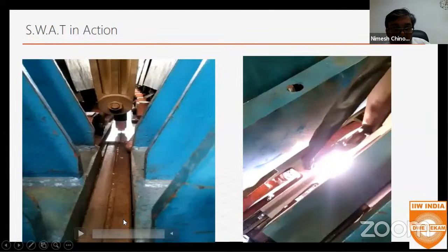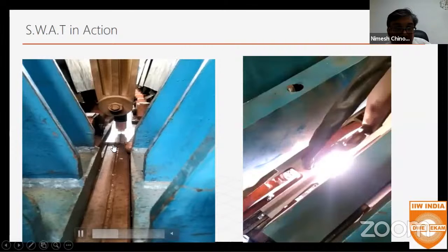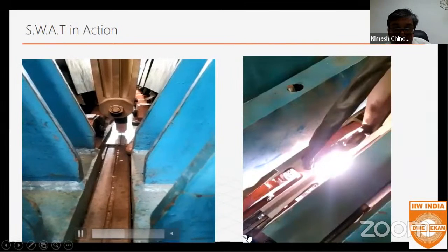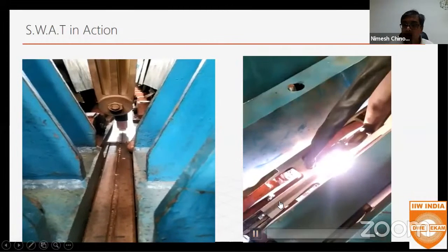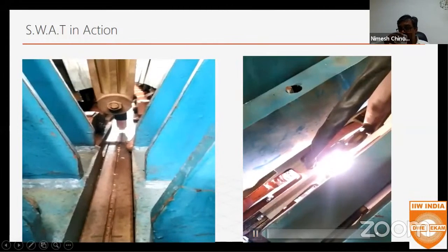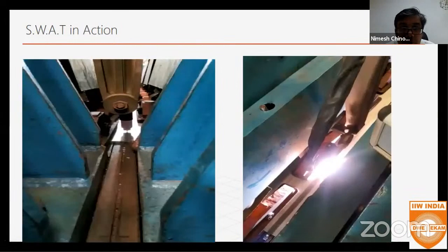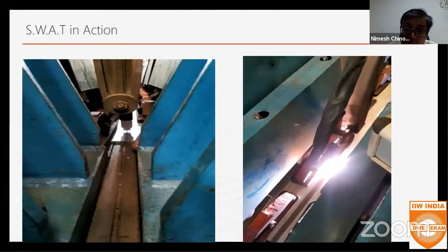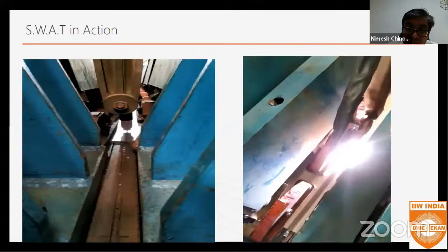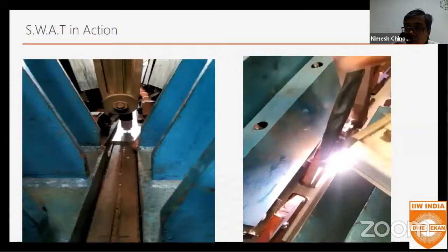This is continuously under production at one of the largest fabricators in India. And you can see here the edge preparation, it's square butt, no edge preparation required. And here on the same fixture, we are doing the welding. This is the actual speed of weld that you can observe. Also, in this case, we are not adding the filler wire in the first pass. So no filler wire, completely welding in one go, achieving the entire weld within 15 minutes is a big change in the output.